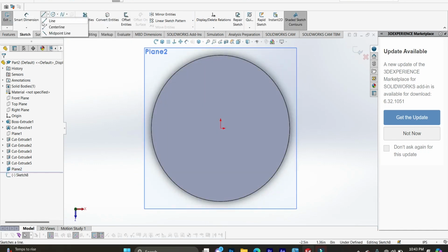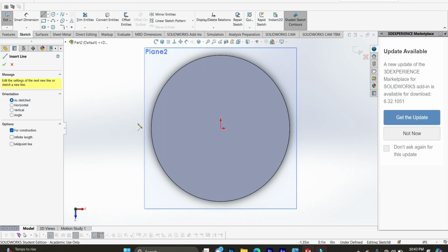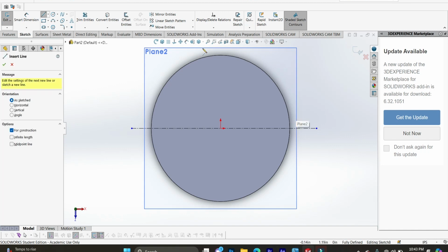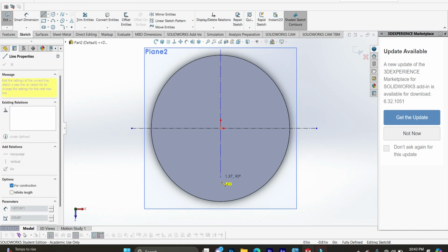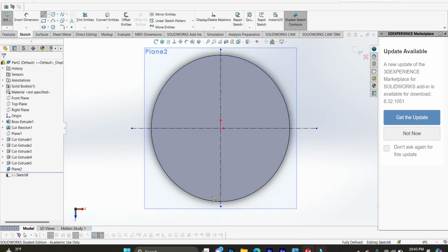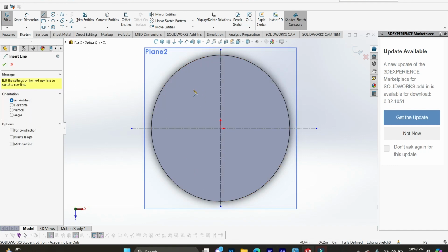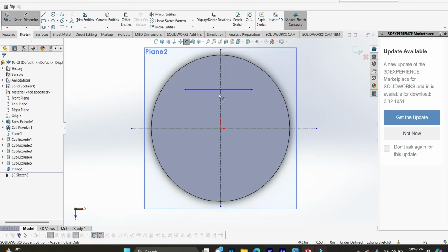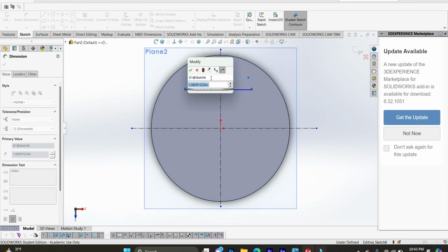We're going kind of to repeat the same sketch as the one we did in Sketch 5. So this one is center line, right? Okay. Two perpendicular lines both going through the origin, and they're both center lines. Enter. Now a regular line. This line has a dimension of 1.60,